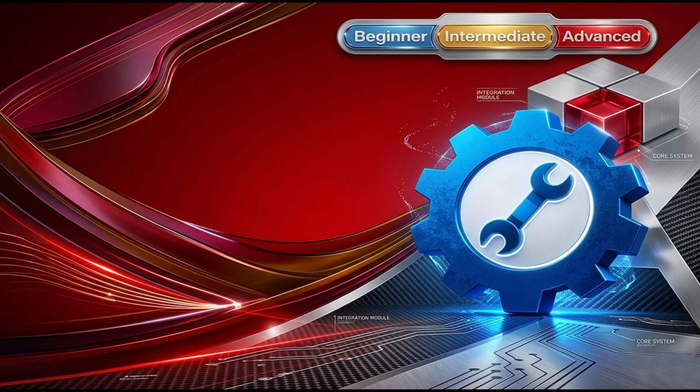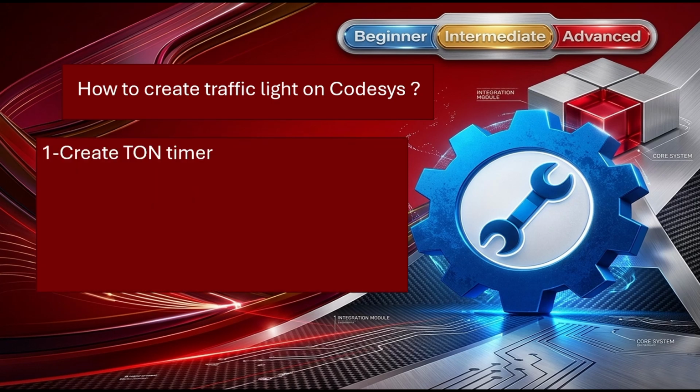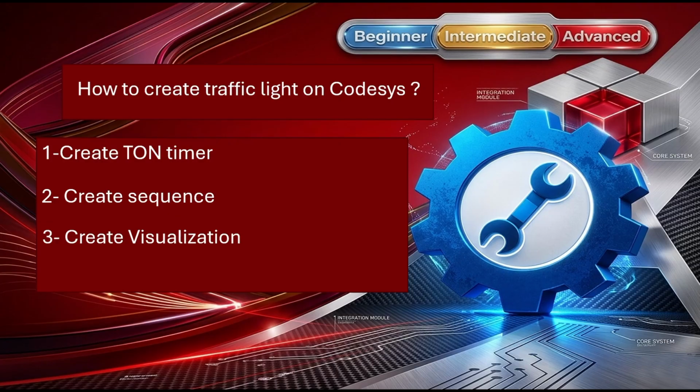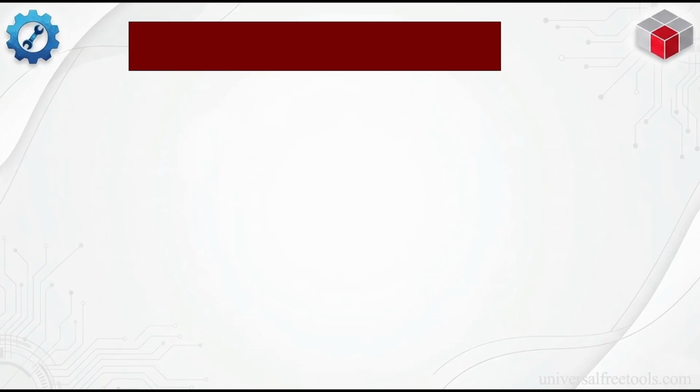Want to build a traffic light in CODESYS? It's the perfect project to master timers and visualizations. Here is the 4-step breakdown. 1. Create a TON timer. 2. Create the sequence. 3. Create the visualization. 4. Link the visualization to the sequence.